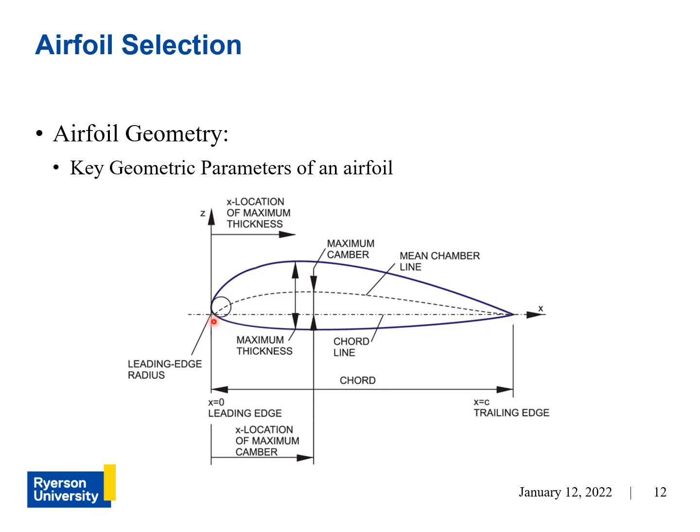Now, camber refers to the curvature of an airfoil and allows for the airfoil to generate lift at zero angle of attack on top of the effect of delaying flow separation. Camber increases the maximum lift that an airfoil can produce, but at the cost of increasing drag and pitching moment. Now, in terms of geometry, there's something called the mean camber line, which is this line here.